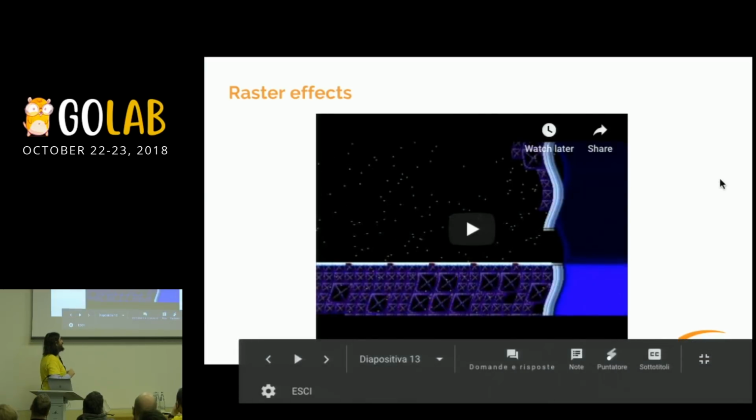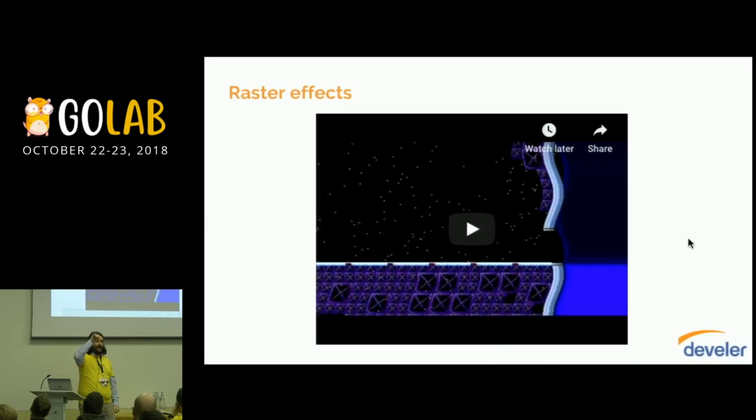So the effect is done by a clever programmer who changes the horizontal scrolling of the GPU every line of the screen with the CPU. It waits one line, and before the second line goes on, moves the horizontal scrolling register a little bit, every line of the screen, synchronizing with the GPU while it's drawing. And so it doesn't need a GPU that is able to actually do that effect. It can just simulate it like this.